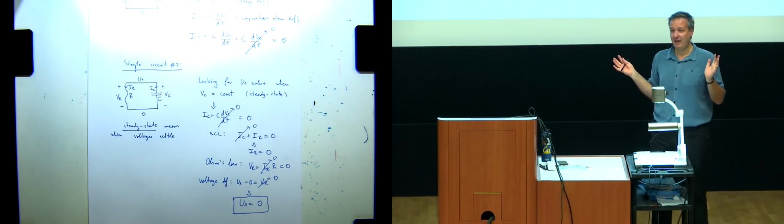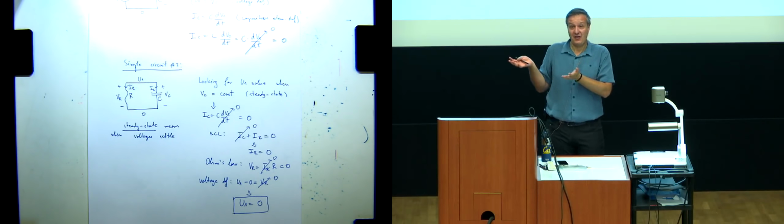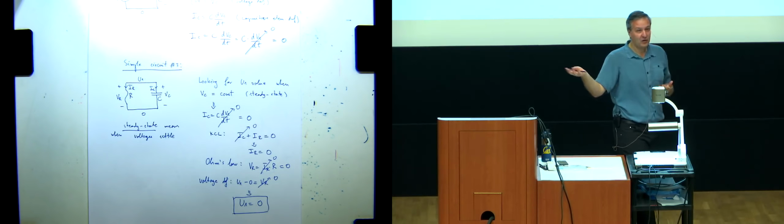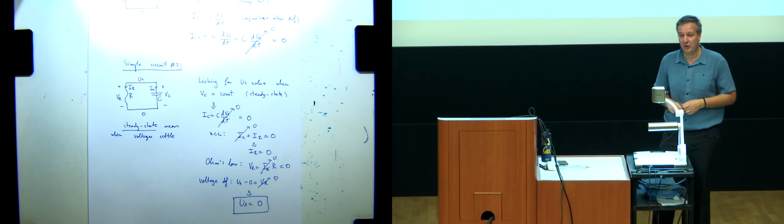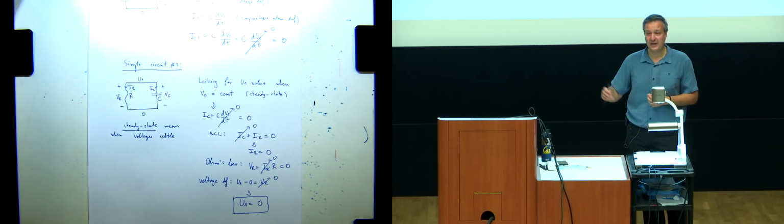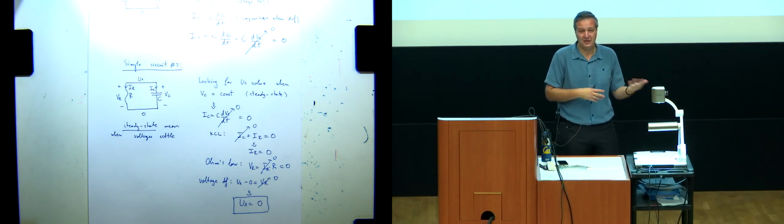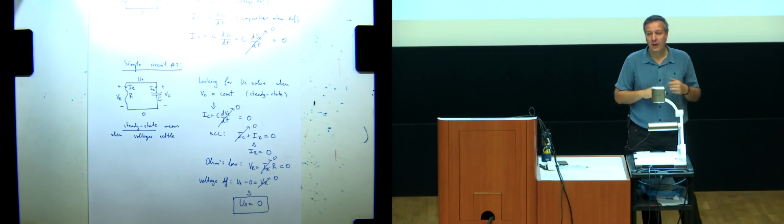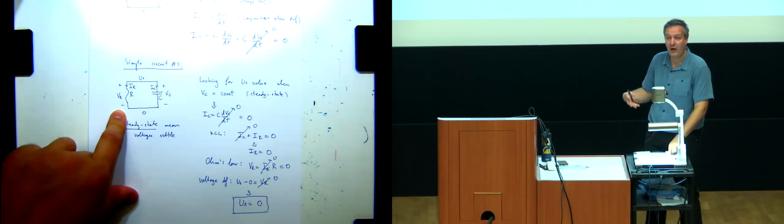We said open circuits are really our friends. They simplify the circuit analysis by a great deal. There's no current flowing, so the circuit gets simpler. Imagine you have a circuit with 10 capacitors, 3 resistors, and 1 voltage source. All of a sudden, these 10 capacitors disappear. They're open circuit, so you only have 3 resistors and a voltage source to solve. That's the type of analysis you can do now in 16A.